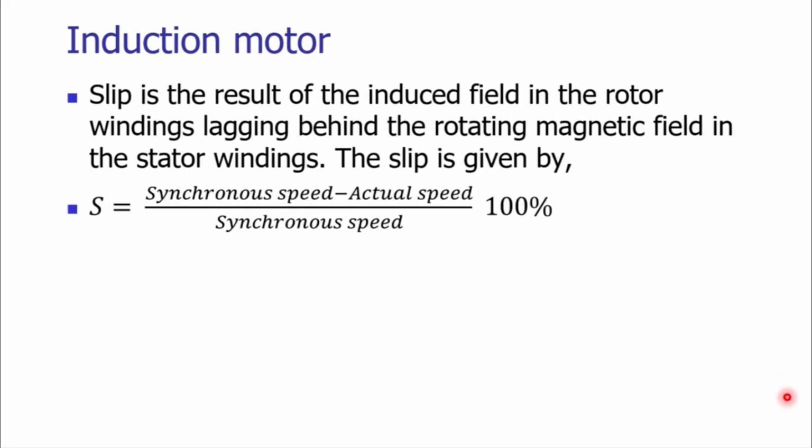Well, slip is a characteristic of the induction motor. Slip results from the lag of rotation of the rotor with the rotating magnetic field of the stator winding.